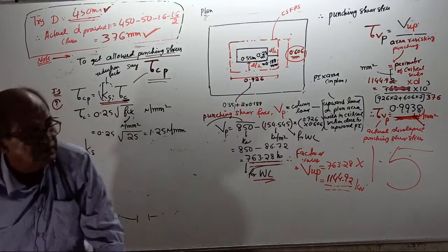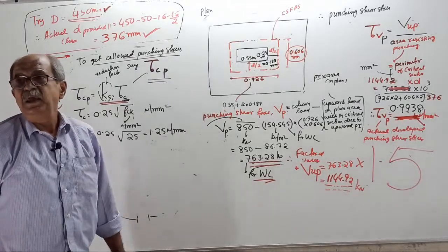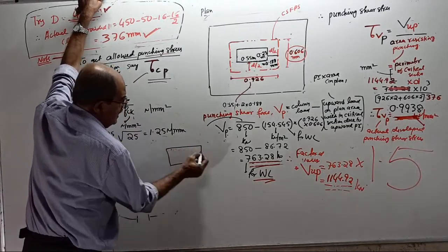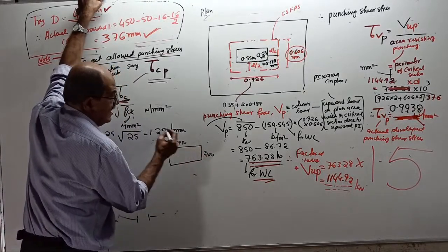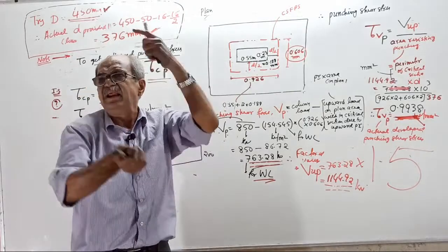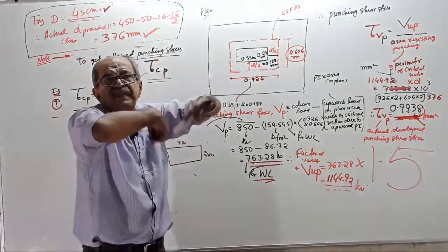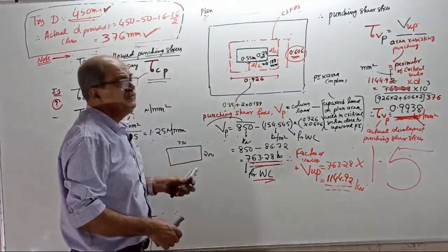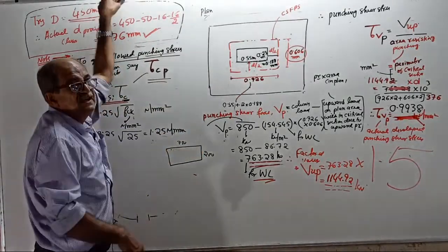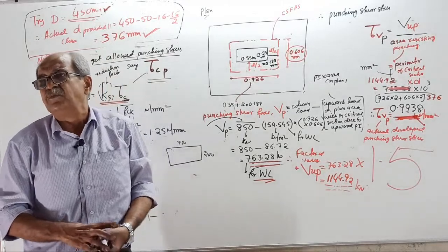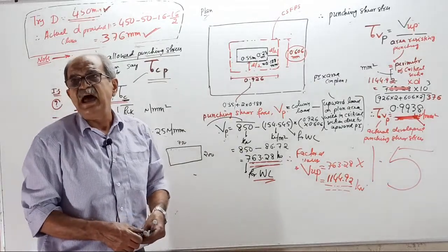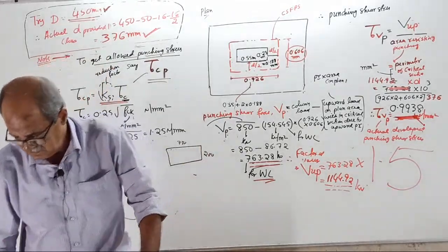Yes, 1. But if it is a rectangular section, say practically nowadays so many people provide 200 by 750. Then tell me, is the punching uniform with the moments also there? See, there will be not only load, BM will be there. Therefore, will the punching be uniform or non-uniform? One side will get high stress, one side low stress. If it is a long rectangular column, think a little. Uniform or non-uniform?